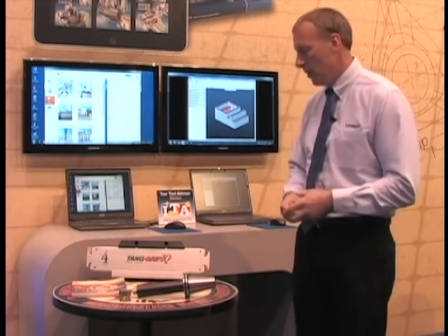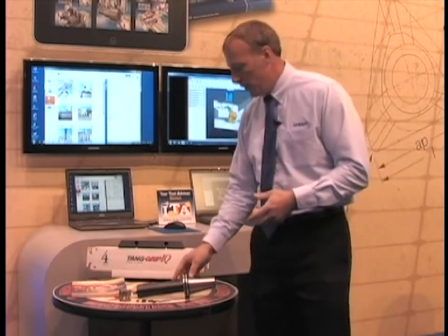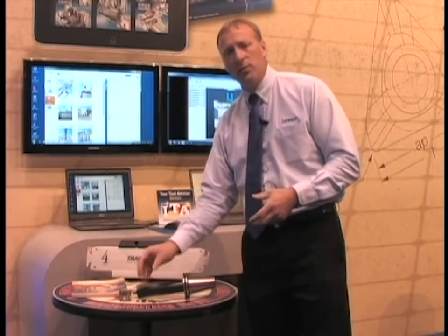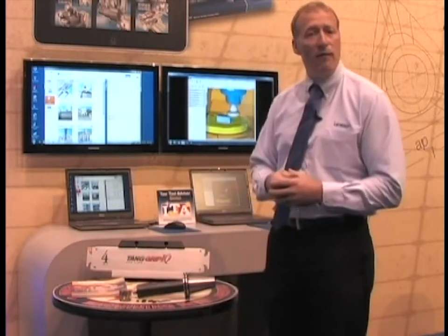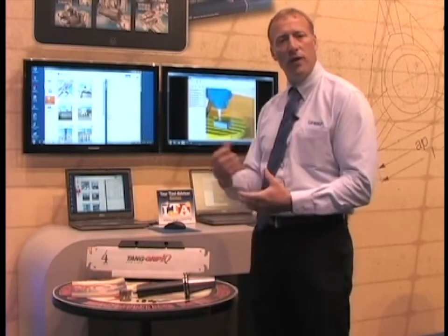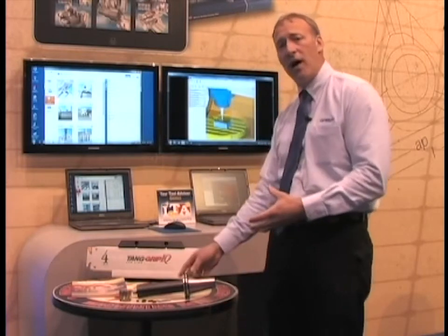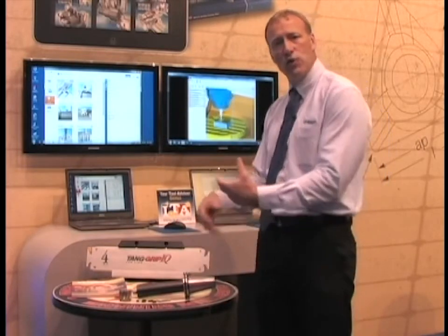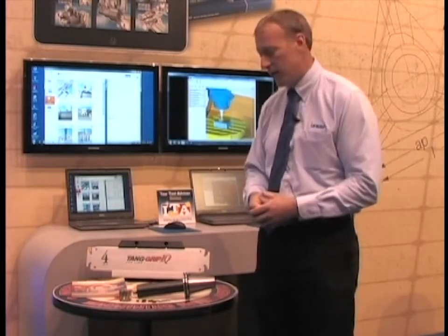tool management. For example, here I have a tool holder, a shell mill, and some inserts that a programmer may have ordered from Iscar, and now the challenge becomes, how do I get this item or these items put together into a CAD/CAM system or the verification system so that they can verify the tool path and that there's no collisions or anything like that before they go into the actual machining process.